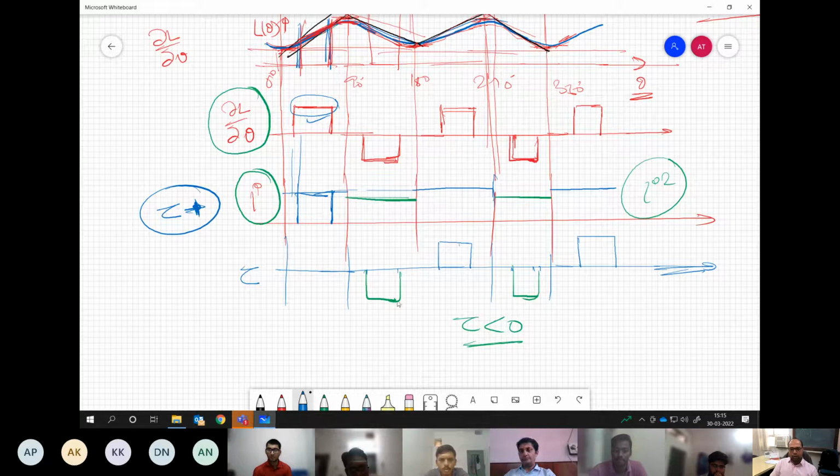We will have alternating torque generated on the machine. But if we want to have only positive torque, we need not apply the current during minus ∂L/∂θ. That's what we have shown. The current applied during this positive ∂L/∂θ, indicated by blue color, would generate the positive torque only, indicated by the blue color.